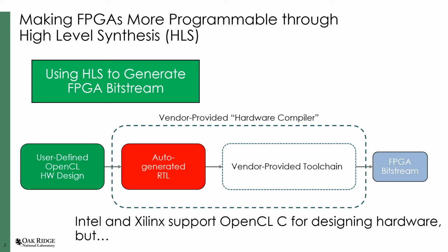Intel and Xilinx, two of the major FPGA vendors, both supply HLS toolchains. In fact, there are many examples in the literature where HLS designs perform at least as good, if not better, than their low-level design counterparts. Moreover, Intel and Xilinx FPGAs can both be targeted using OpenCL C. Thus, in theory, designs for one FPGA should be portable for the other and vice versa. The implications of this are immense, as developers could easily move designs from one FPGA to the other. However, the question of portability and performance in this context is not as well examined.